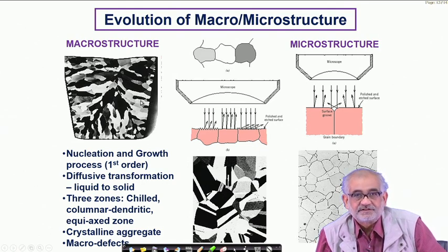And if the orientations differ, because of their crystalline nature, they carry different densities of atoms as manifested on the cross-sectional plane with which they coincide. And since the atomic densities are different, they have different degrees of reflectivity. And because of that, we are seeing different colors or different lusters of these crystallites. This actually is a macrostructure which is possible to be seen even by the naked eye. But when we want to go deeper and understand even more, then we go into the realm of microstructure.